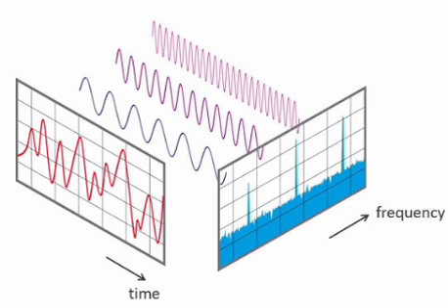aⁿ cos(ω₀n) u[n] ↔ (1 − a cos ω₀ z⁻¹)/(1 − 2a cos ω₀ z⁻¹ + a²z⁻²), |z| > a. aⁿ sin(ω₀n) u[n] ↔ a sin ω₀ z⁻¹/(1 − 2a cos ω₀ z⁻¹ + a²z⁻²), |z| > a.